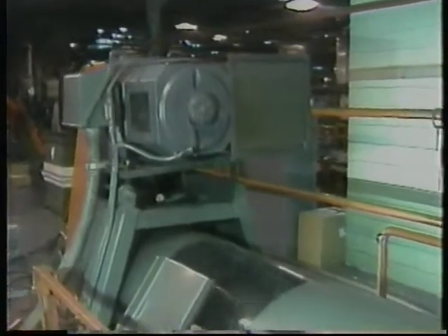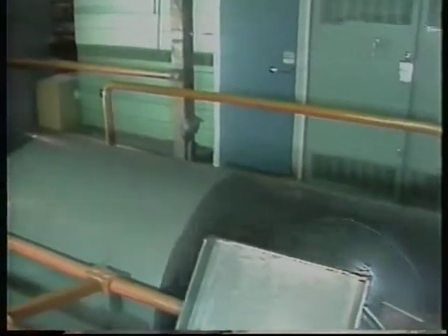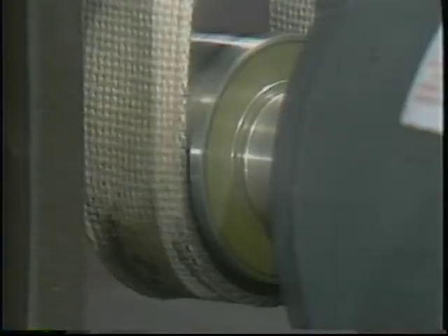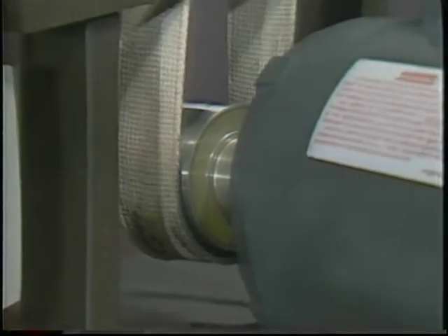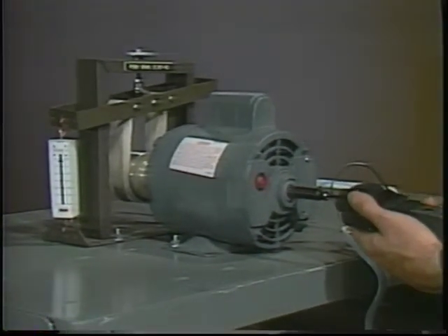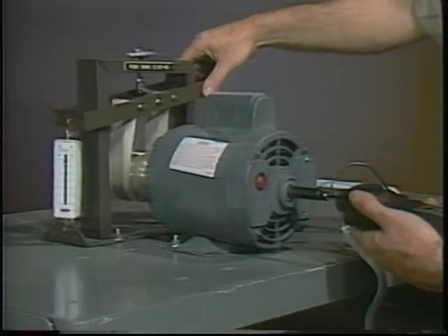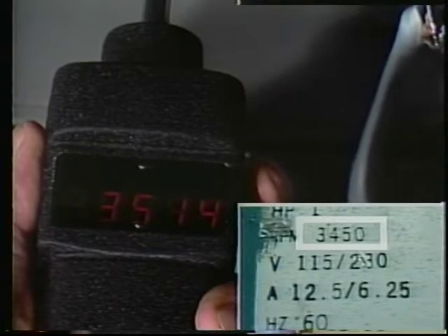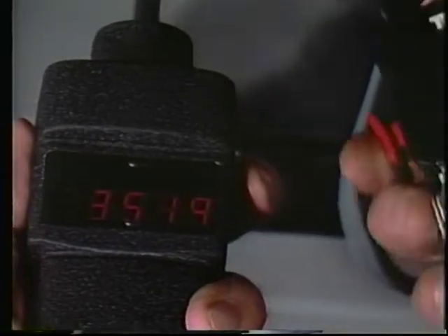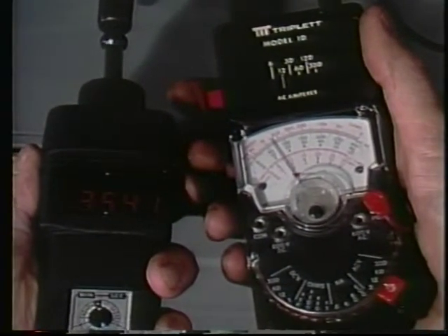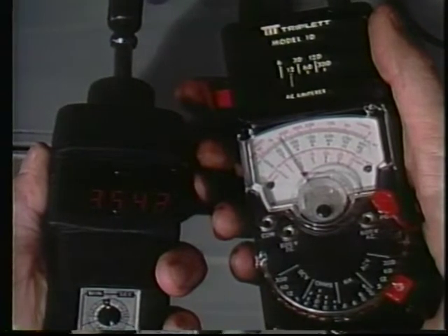Okay, we've seen how a motor is made so that current produces magnetic fields, and how the magnetic fields produce torque and horsepower. Now let's take a closer look at the general operating characteristics of motors, how they behave under various load and speed conditions. We'll start with a motor running under no load. The shaft is turning freely at full or maximum speed, usually somewhat faster than the speed stamped on the motor nameplate. As you can see, even an unloaded motor draws some current. That's because the motor must overcome bearing friction and the wind resistance of the spinning rotor and fan.